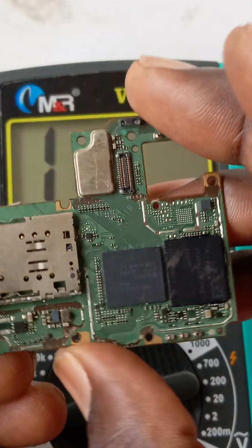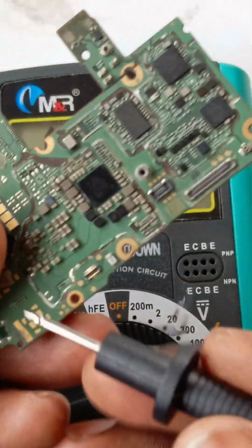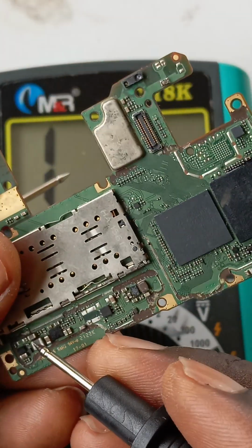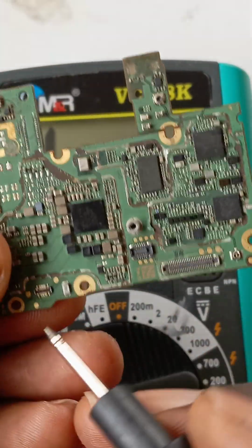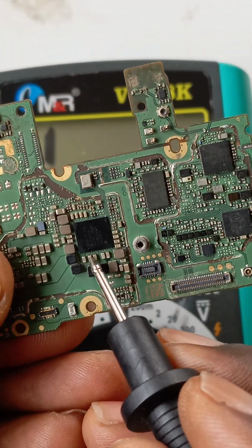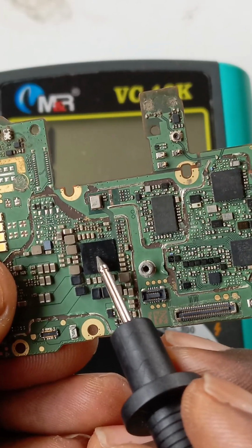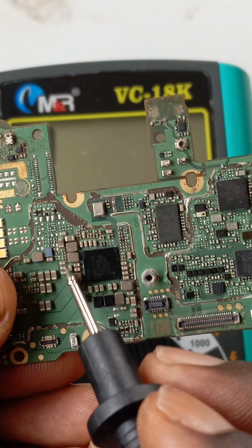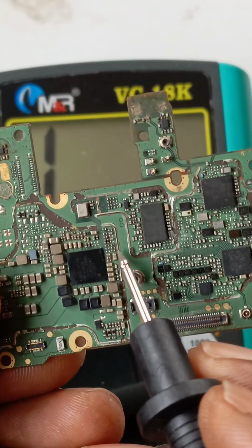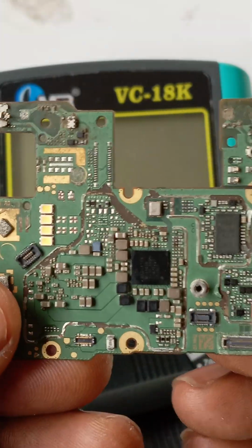Here you can connect the battery, and then you check. You connect the battery here, then you check the voltage from here. If you see the voltage here, that means the voltage has come to supply the power IC through these capacitors. You also see the same voltage here that is going to enter the power IC, and the power IC is going to boost that voltage into different voltages and then distribute it to all these components that you see here, that are going to take the voltage to the other components or sections.